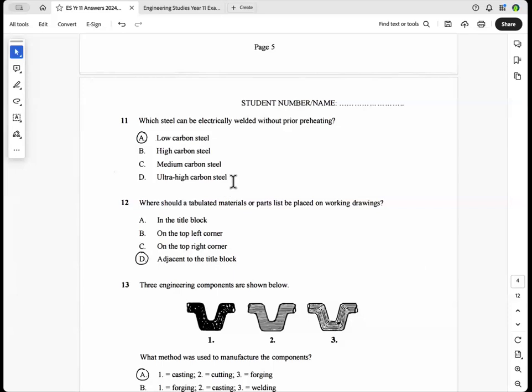And because of that high temperature, it will cool rapidly. And if it's got a high carbon content, you'll get martensite forming because you're virtually quenching it from 5,000 degrees. And so you've got to preheat ferrous metals that are above about 0.3%.